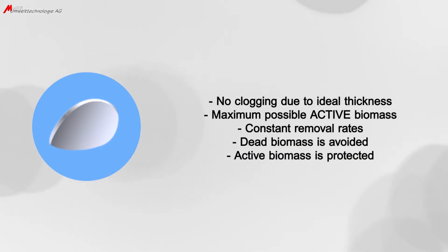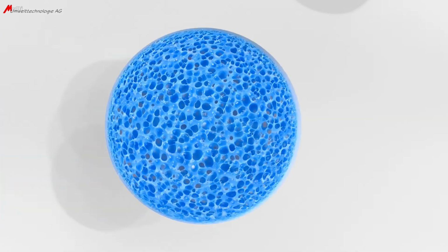On the other hand, there is no need to worry about a potential loss of active biomass on the Mutag BioChip. The biofilm establishes inside of the pores, where it is protected against being flushed or sloughed off by the self-cleaning effect. In other words, the geometry of the Mutag BioChip ensures that the maximum possible amount of active biomass can be permanently kept on the carrier. Dead biomass in the pores will be metabolized and displaced by active microorganisms, whereas the pores are permanently filled with active biomass.